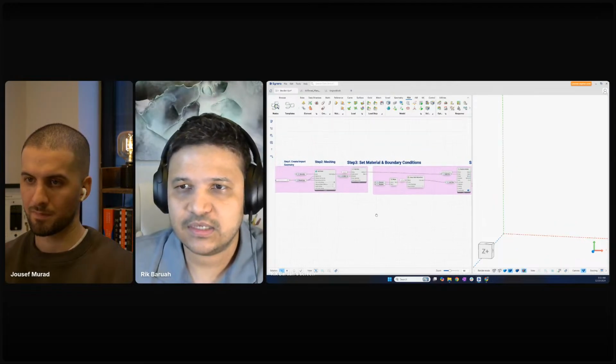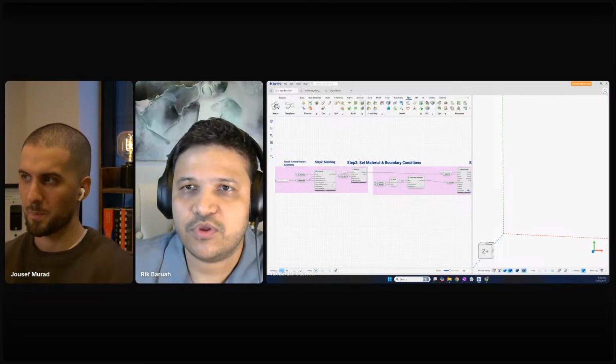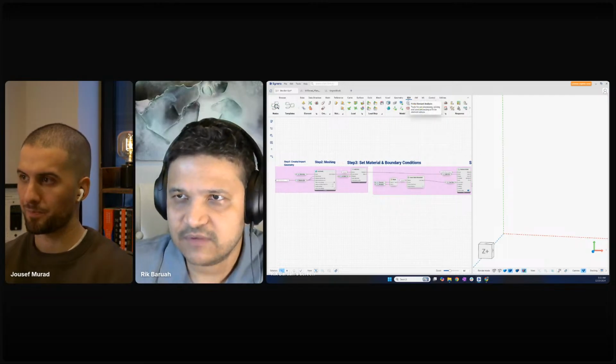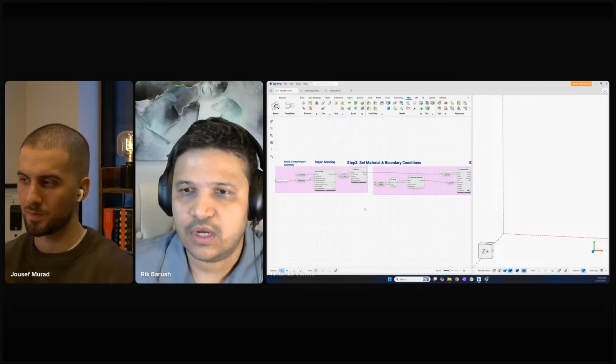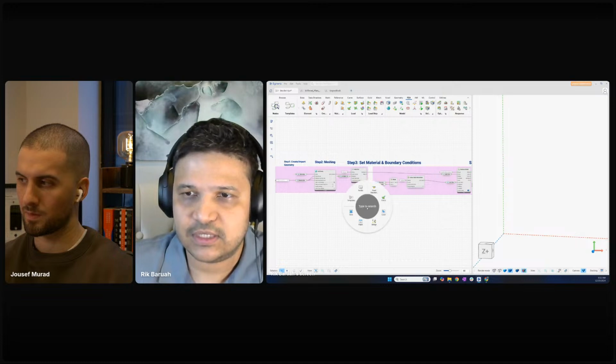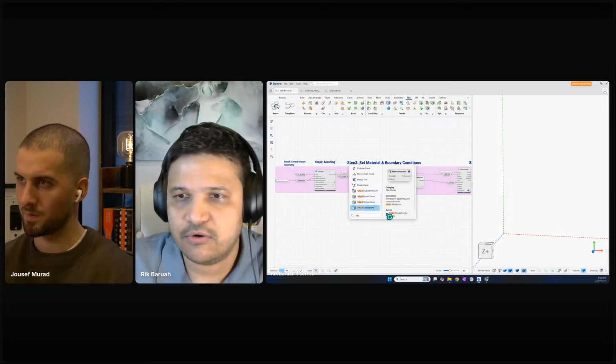With Intact, what we're doing is really simplifying the process. Intact is a module within Synera. It lives in the FEA tab. In the model section, you have your component. Under solvers, we have our modal solver and stress solver. A quick way to find things in Synera is also to double click and type it in. So here you go, Intact component.